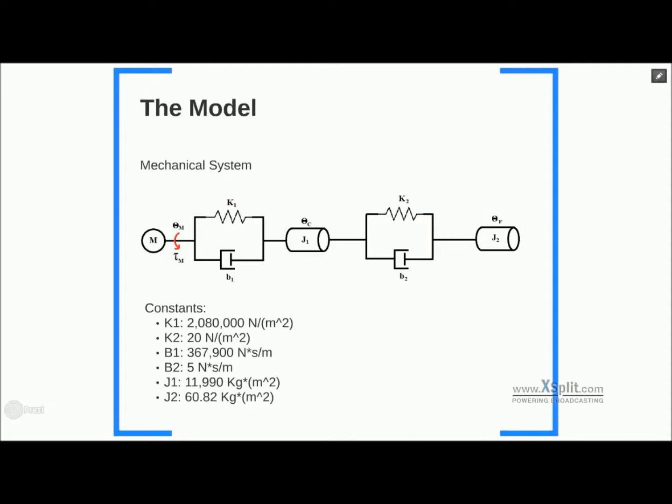Yeah, and actually it's interesting. The cable is a little difficult to model because when you're looking at just the radial position of it, you can't really talk much about the properties of the wire stretching, but it's more just modeling the back and forth movement, which is why, as we talked about, we looked to see the response. We actually found how long it would take a pendulum of the same length to make one full revolution, omega-wise, and then modeled our system to fit with that behavior, the real-life behavior of a big swinging load. So that's why those seem hand-wavy, but there's a reason for those as well. And we'll see a plot of that later, right? Yes, we will.